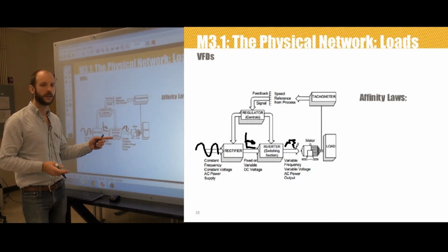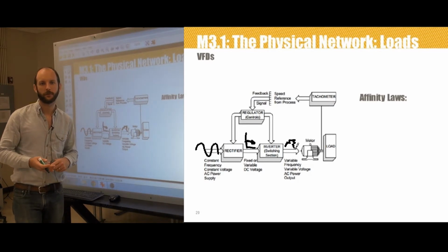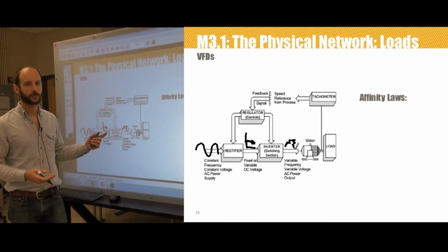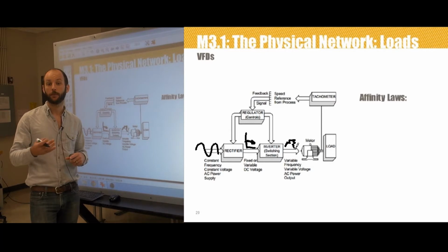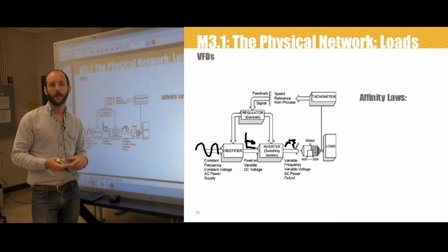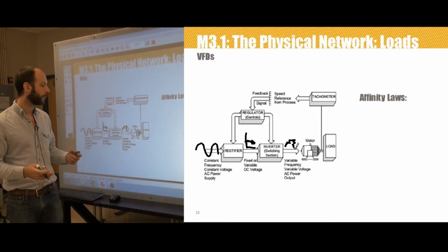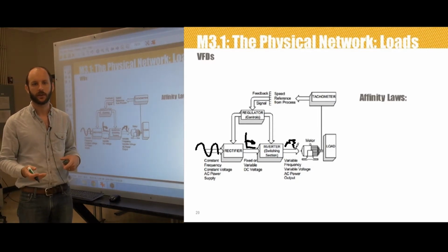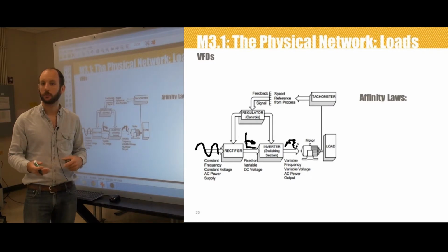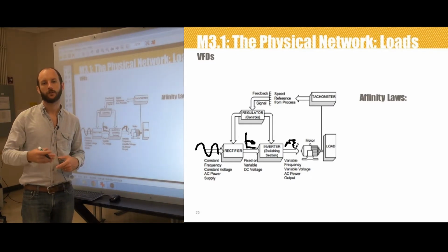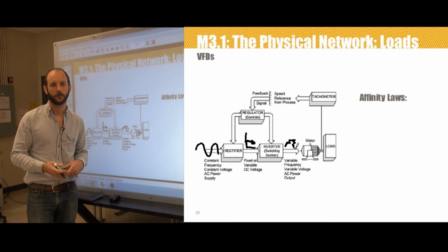The use of a VFD, however, to vary the speed of fans and pumps during times when the motor-driven pump doesn't need to operate at 100% can therefore achieve significant reductions in energy use as compared to the traditional methods of using these mechanical throttling devices. And this is becoming an extremely common application of VFDs, to replace these mechanical throttling devices.